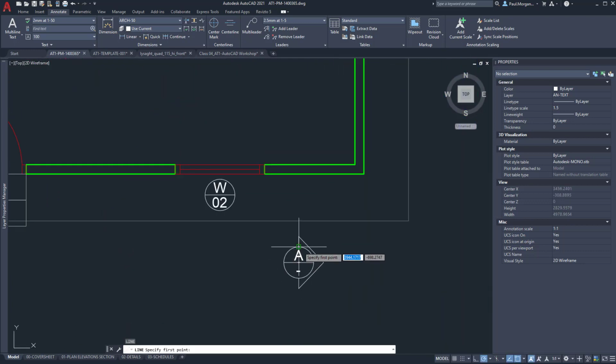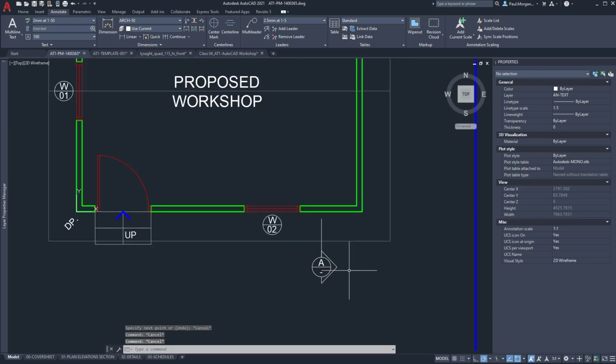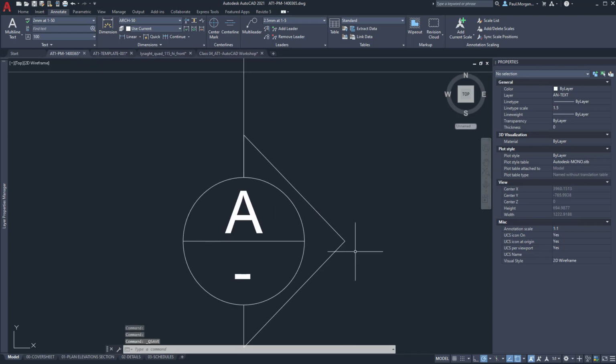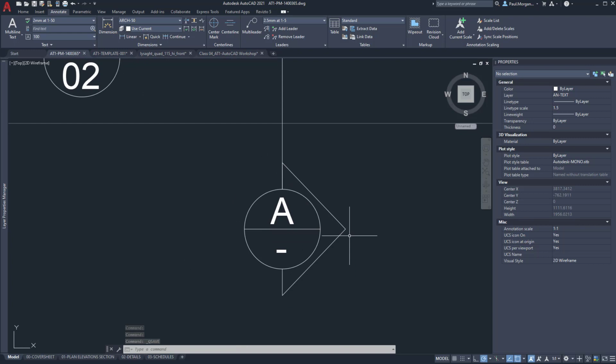And we need a line that's going from here over something like that. So what I'm going to do is hatch this area in. Hatching is essentially a pattern or a fill, and I'll go through hatches in a little more detail shortly, but just for this instance we're going to do a solid black hatch. Now one tip for you guys, please make sure that you save your file before you start hatching. Hatching does have a tendency sometimes to crash the file if the area is quite complex, so it's always good practice to save your file before, in case it does glitch and crash.